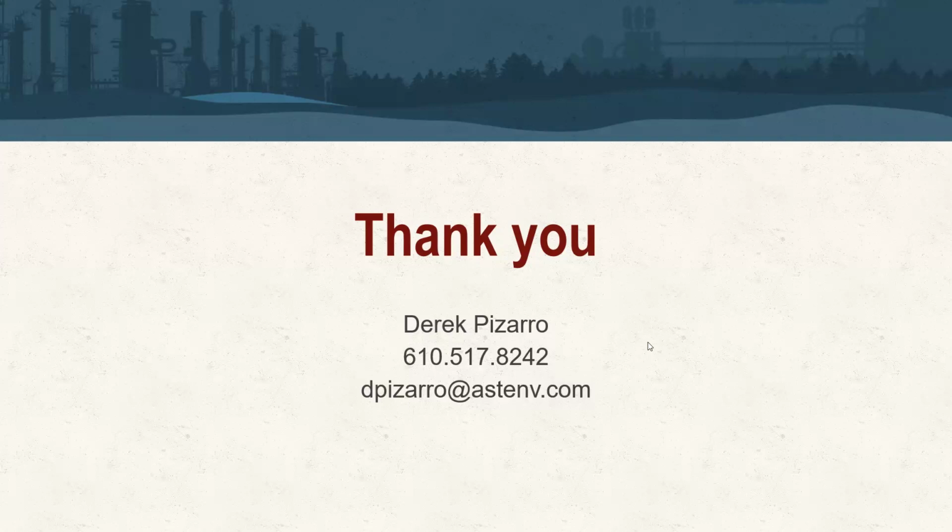And then from a persistence standpoint, because we have a slurry product, we have a mixture of soluble and partially soluble sulfides. We have that continued treatment and maintenance of those parameters that we're looking for. So I think it would be very easy with some piezometers, some implants, some temporary wells to immediately monitor, and then subsequently over a period of time, depending on your well permitting, you can continue to monitor those parameters very easily through grab samples.